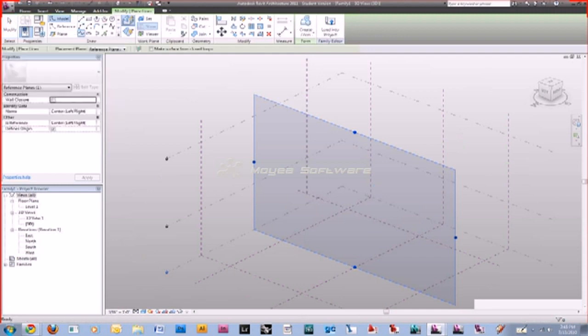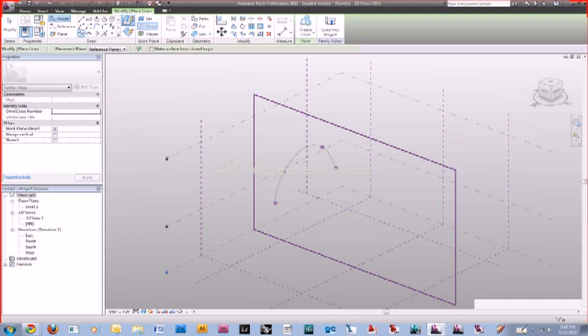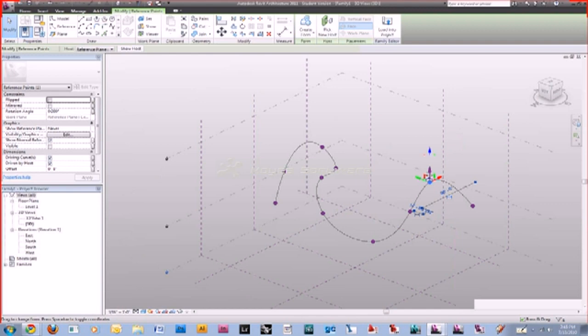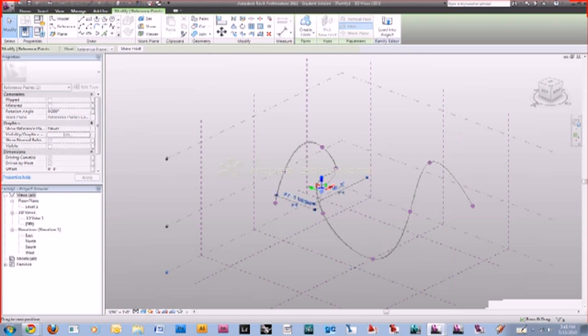So the tool he's using right now is called the spline tool, which is the first thing I think of when I think of a sweep, is splines. And splines kind of readjust themselves based on the next point you put in the project. And so if you go back in and edit one of those points, it's going to readjust itself with the other two lines, which is really neat. So you can start with a boring shape, and then you can start to really make the curves look nice. So maybe you don't like the curve in that little area, so you move it down to make it more of a smooth transition. It's really nice.